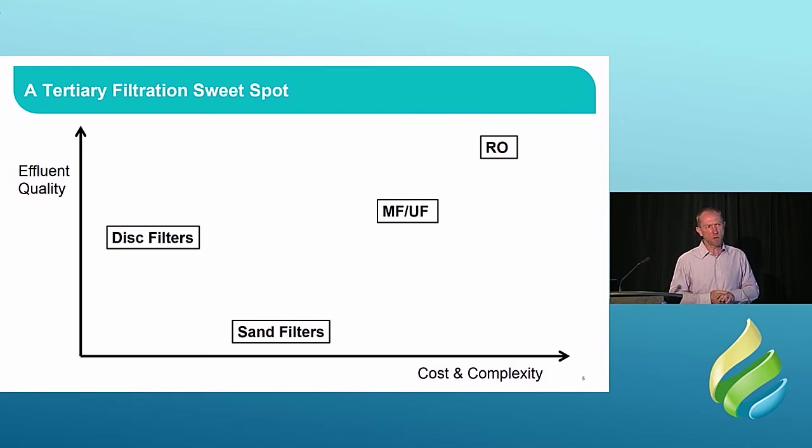The other part of the question was TSS load. Maximum TSS load. How these filters are designed, certainly how the Hydrotech filters are designed, is based on TSS load. You have a filter area. You are able to pass water through that filter cloth at a specific rate, meters cubed per meter squared of cloth per hour, based on the amount of TSS in it. So TSS load is a key design parameter that we need to know to be able to size the filter. Bottom line is the higher the concentration and the more flow you have, therefore the more load, the more filter cloth you're going to need.